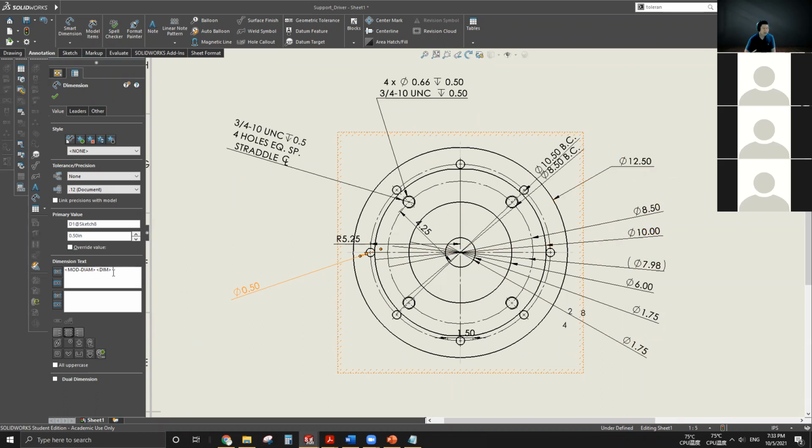And you need to add whatever you need to let the machinist know about your feature. So same thing as this. This 0.5, it has eight places, right? So of course we're gonna say 8 places, or everything must be capital. Remember, every note must be capital. So 8 places or 8 holes, whatever you think is better to describe it.